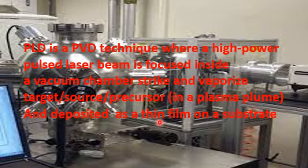So in simple words, in the pulse laser deposition technique, a high energy beam is focused onto a source or target or precursor material. Due to this high energy beam, the material is evaporated, transported onto the surface of the substrate, and converted there into highly crystalline oriented thin films.